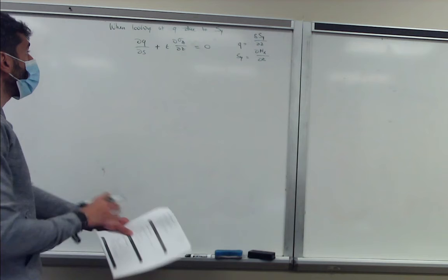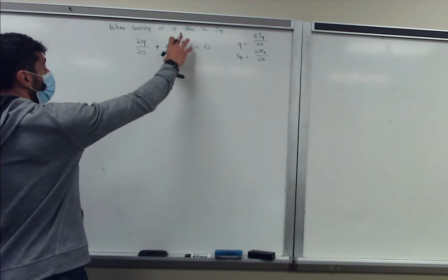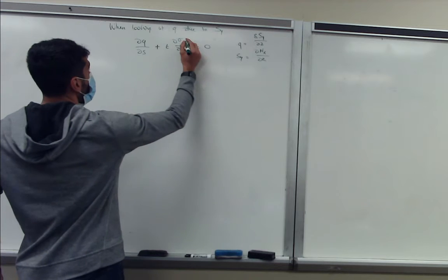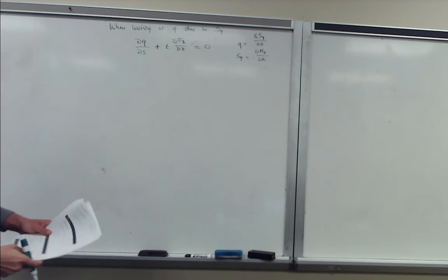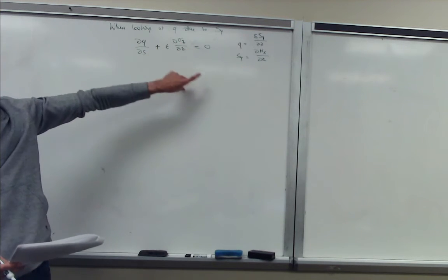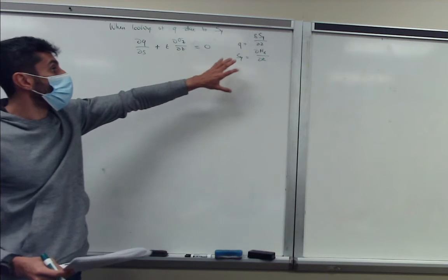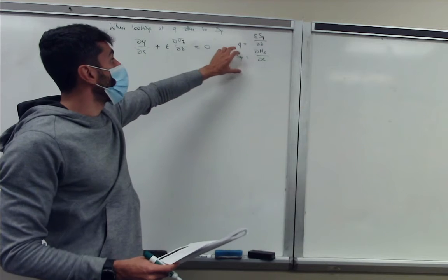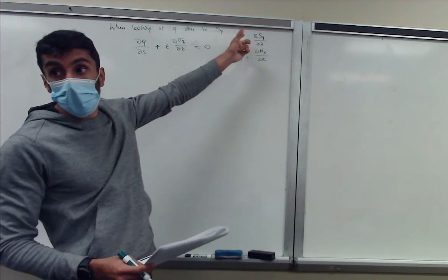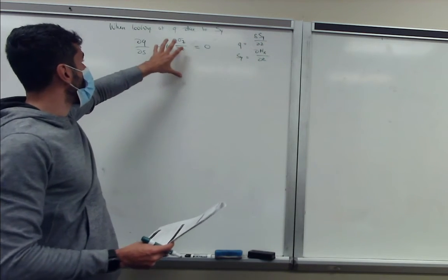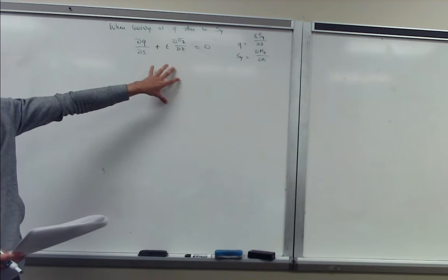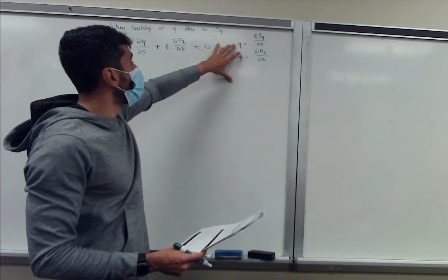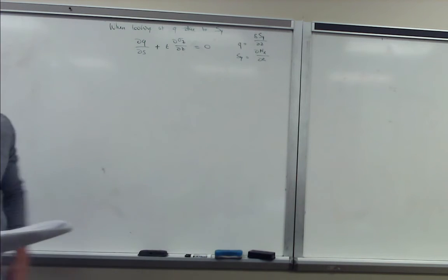So what we next do is recall our equation for direct stresses, because this is what we already derived in our bending, an equation for direct stresses as a function of moment. Here we have a relationship between the moment and a shear force, and here a relationship between shear force and shear flow. So by using those three components, we can combine them into one where we can identify shear flow as a function of our shear force.